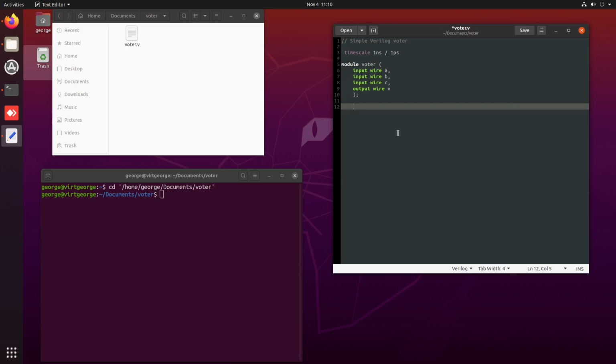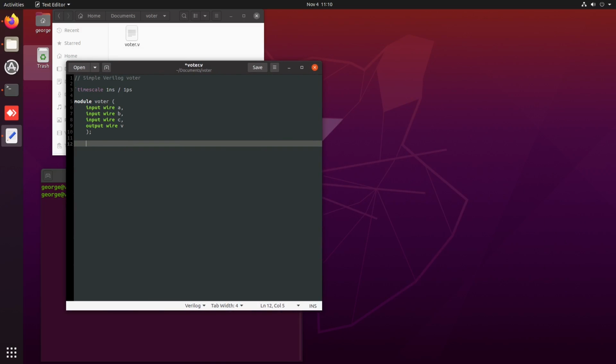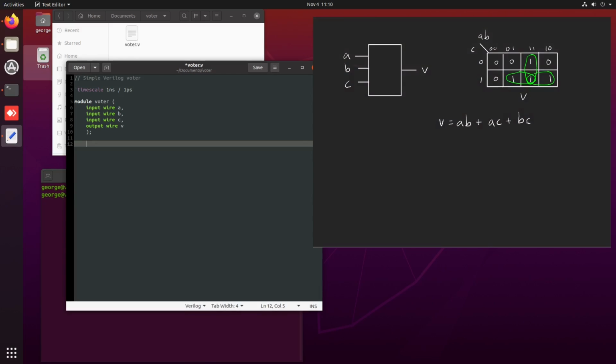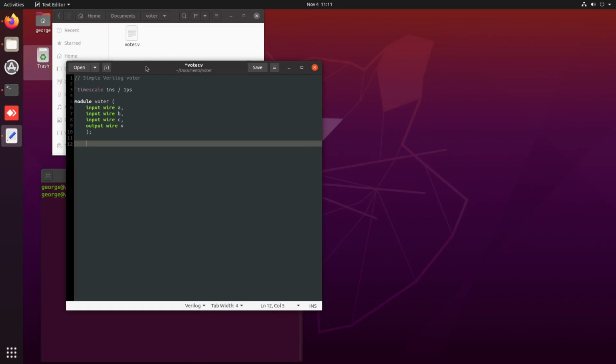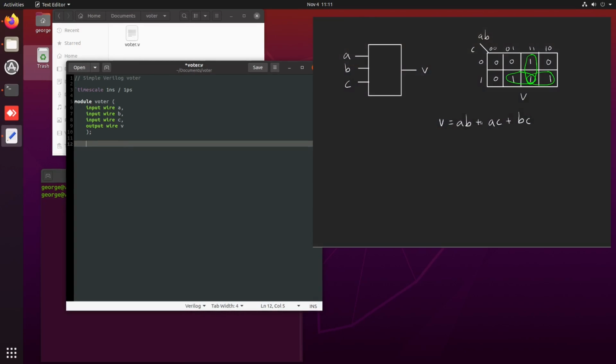Now after the declaration, we need to describe how my circuit is going to operate. Once I have the function calculated, as we have done before, we can simply use that expression in an unconditional assignment in Verilog. It means I can describe the output as the permanent function it does, depending on the variables, which is a direct translation of the logic function I want.